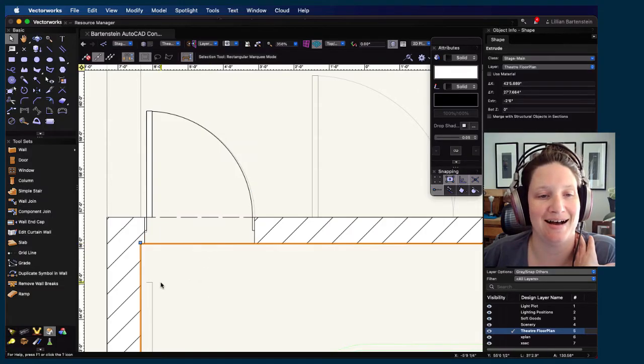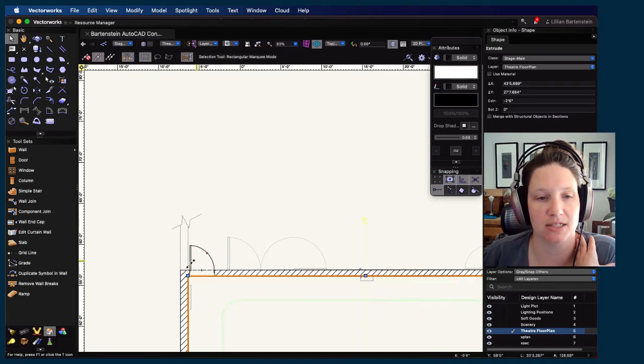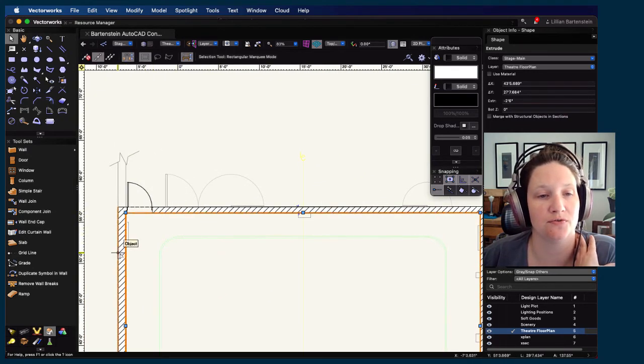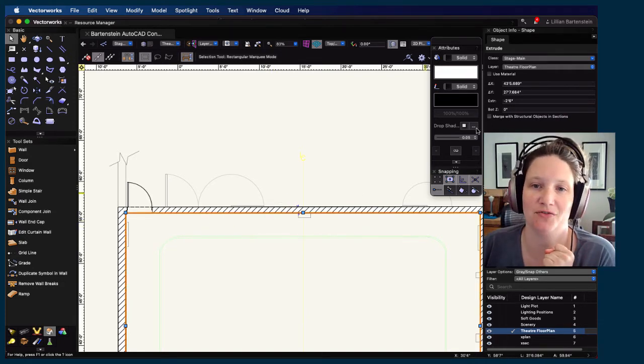We are not seeing it on the other side because of the placement of the deck, right? Because we didn't extend the deck out underneath that wall. If we wanted to adjust it, that's pretty easy to do. So why don't we go ahead and update it so that the floor goes all the way out to the outside edge of the wall? No, better idea. We're just gonna turn off the line on the floor.